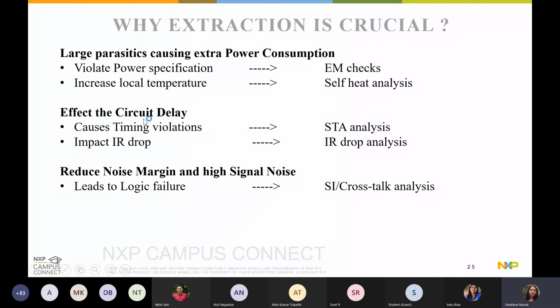If we talk about timing, it is very critical for all stages of the physical design. Whenever there are timing violations, the STA needs to run and check the physical netlist at all stages, and any iterations in the design need to again go through this STA analysis to fix the timing violations. So delays, timing, parasitics, they all come through the extraction part.